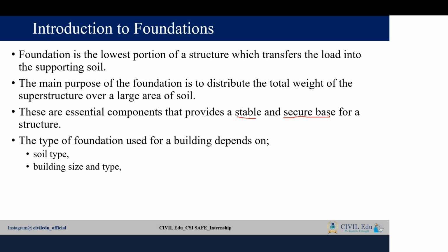Suppose you are constructing a hospital. Now, we can expect that in a hospital, 24 by 7, people will be there. That means huge amounts of live loads will come into the picture. When huge live loads are coming throughout the day, you need to go for a different type of foundation. So, based upon the type and size of the building, the foundation has to be decided. I'll be talking about these details very soon.